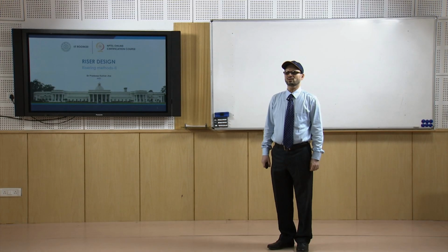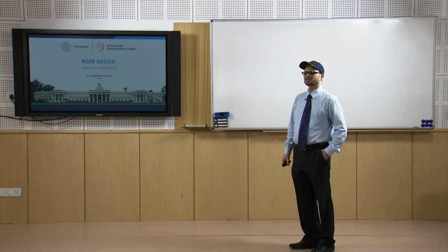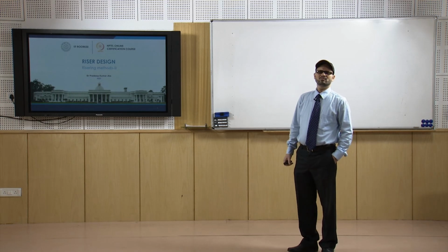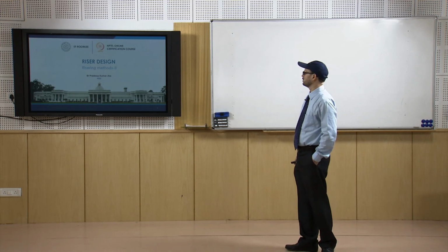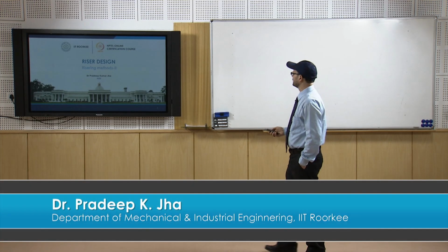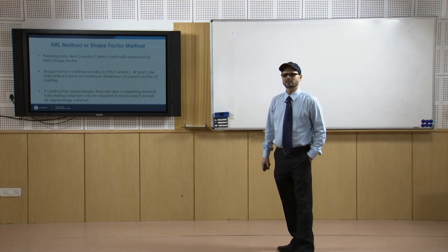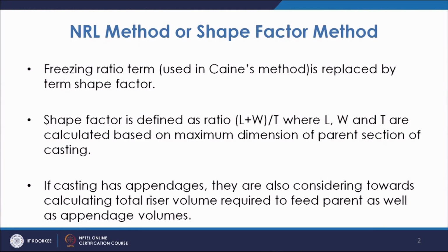Welcome to the lecture on riser design. In this lecture, we are going to further discuss another method for calculating the riser volume. So, we are going to discuss the shape factor method, also known as the Naval Research Laboratory method. Here we are going to use this parameter, shape factor.